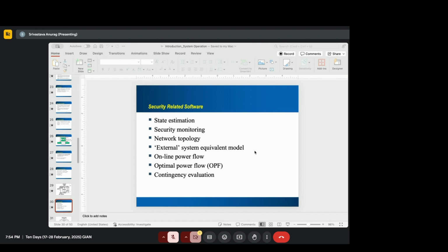So in terms of accuracy, PMU is being installed at newer substations, because it requires a faster communication network. We cannot put that on the older ones because the communication bandwidth is already used there. So we are putting the PMU at substations which are newer and have more communication bandwidth.